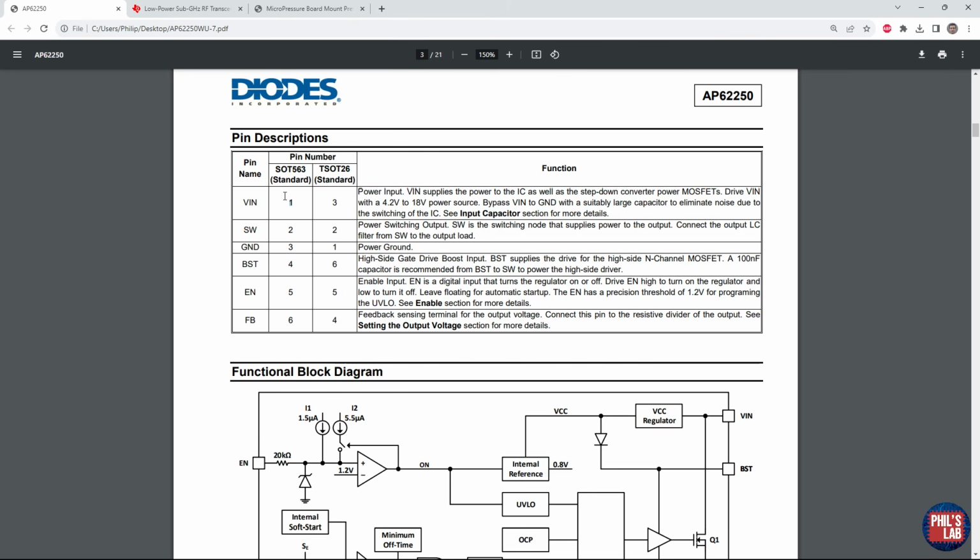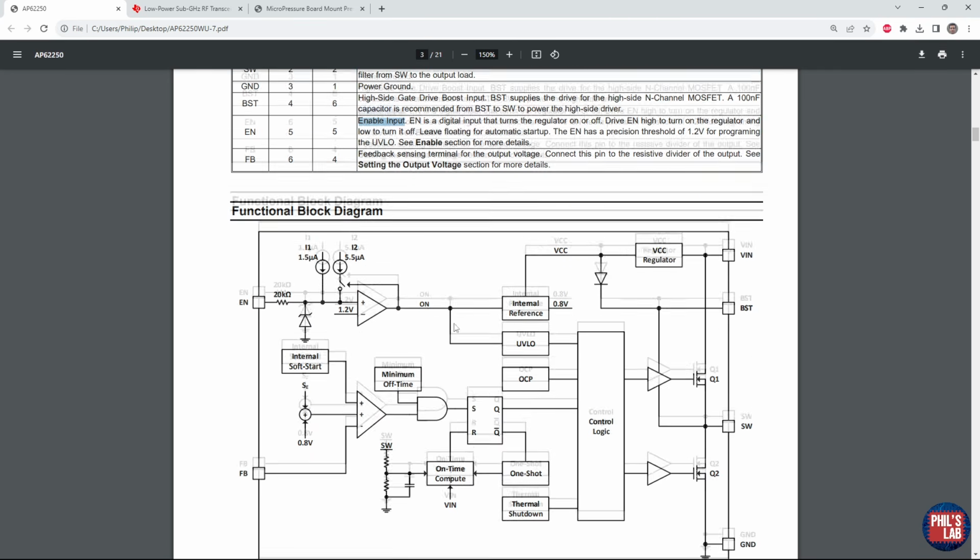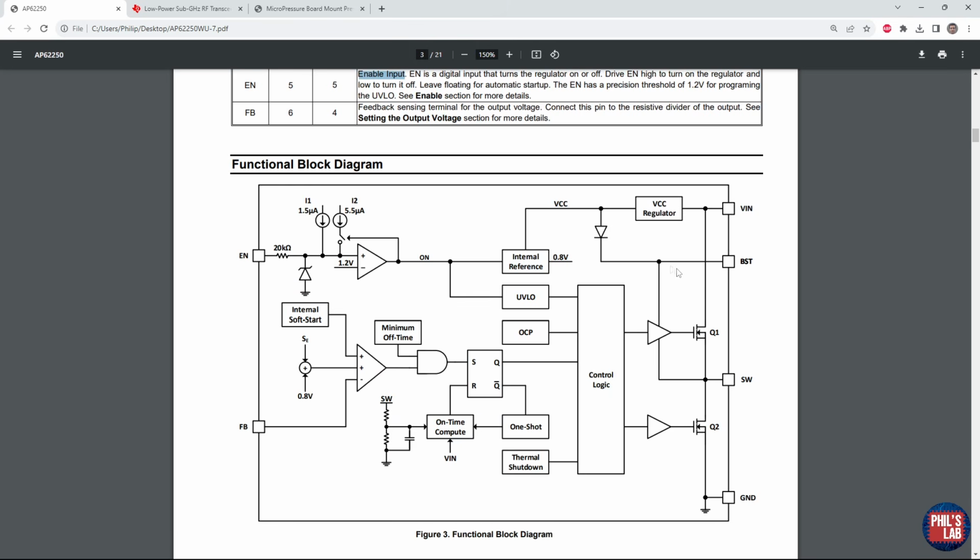So that would move that over to my ECAD tool, be that Altium Designer, KiCad, or whatever, and label that then as a power pin. Similarly for the enable pin, that's pin 5, and that I would select then to be an input pin. And this is how I can create my schematic symbols. Typically accompanying that, you might get a top-down view of the package or some sort of functional block diagram where the pins are labeled, and you might get to see the guts, so to speak, of your part.